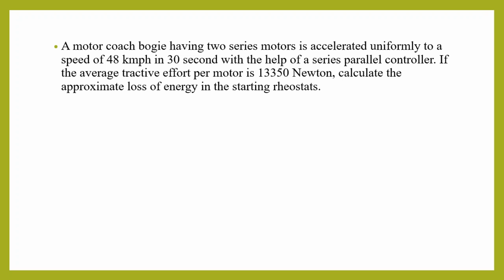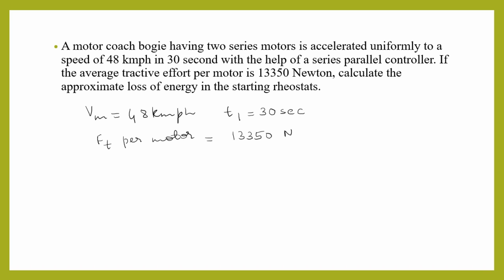So we have Vm equal to 48 km per hour and the time duration is 30 seconds, that is T1, and tractive effort per motor Ft is 13,350 newtons. So Ft, the tractive effort for the two motors, is 2 into 13,350, that is 26,700 newtons.